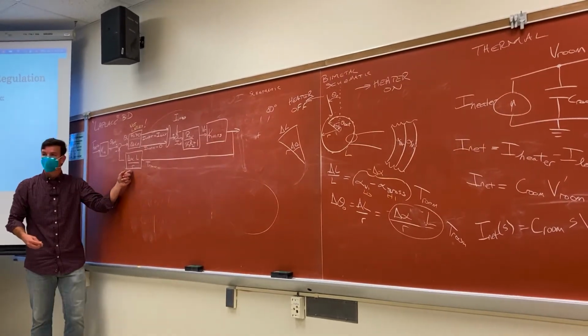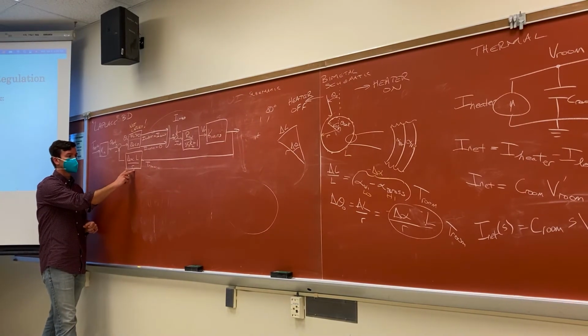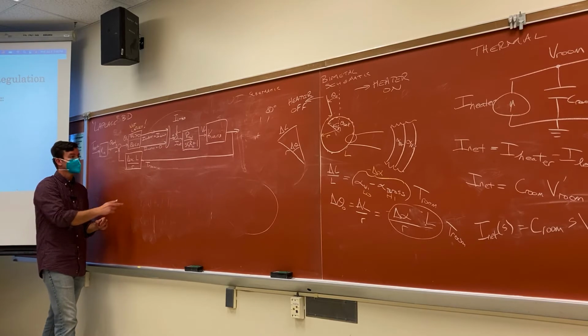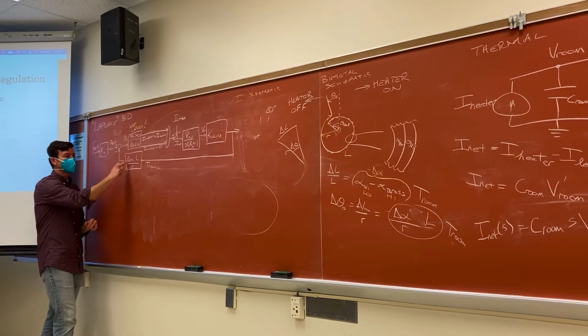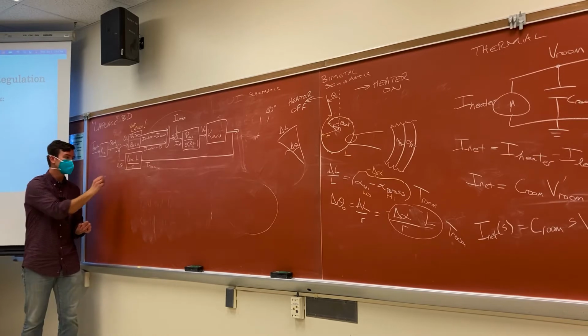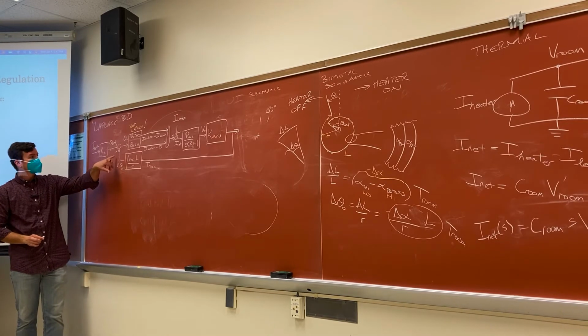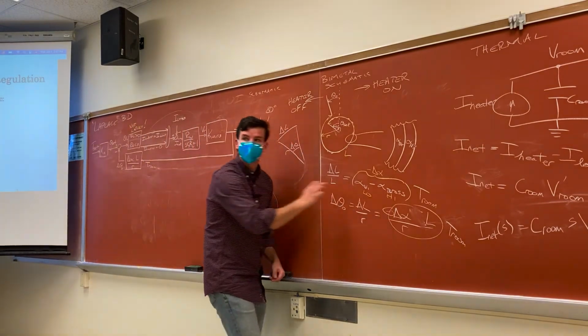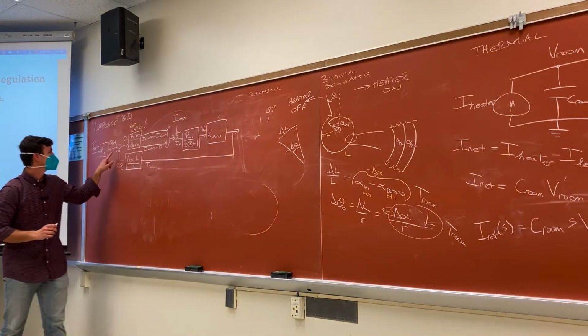And that's exactly what I've done here. So this is a transfer function, but it's actually just a scaling factor. Because I'm taking the temperature in the room, I'm scaling it by these parameters, and I'm getting delta theta O, which I'm then subtracting because I omitted this negative sign from the box, and I moved it up here.